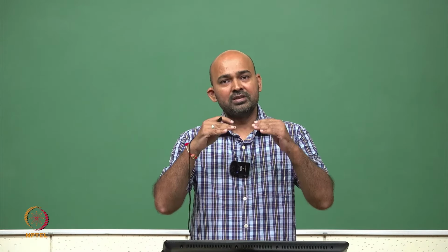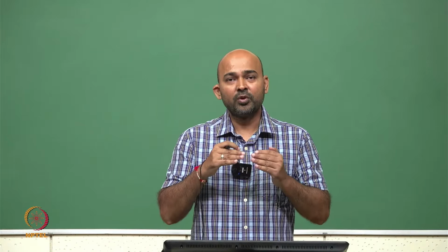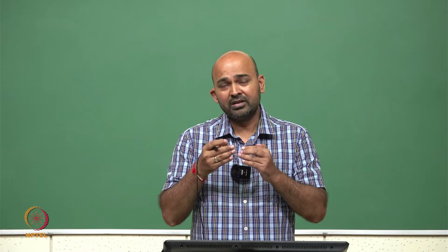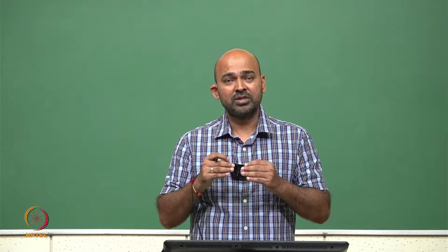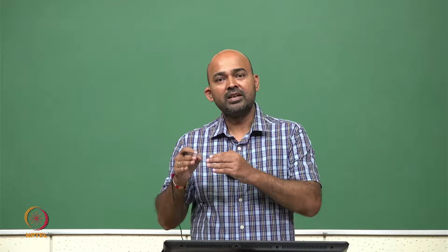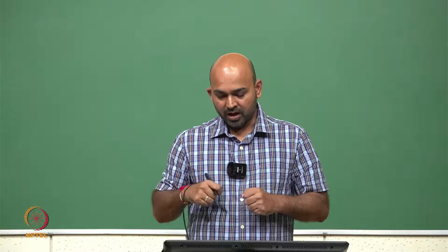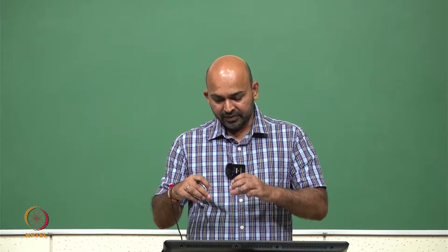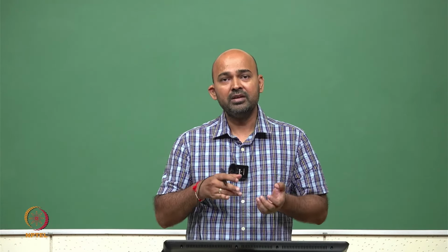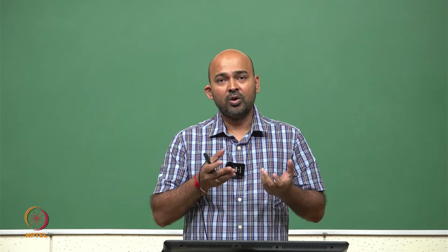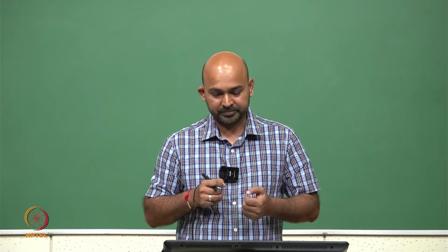So, we need to have certain margin or certain overlap, so that because of the mismatch, if this 4.8 becomes 4.89 or 4.9 or 4.75 or something, still that value is detected by the input of gate B. So, we need to have a little bit of mismatch or overlap between input and output. So, based on these definitions of logic levels, now we can write the definition of VOH, VOL and VIH, VIL, which are the logic levels for these logic gates.